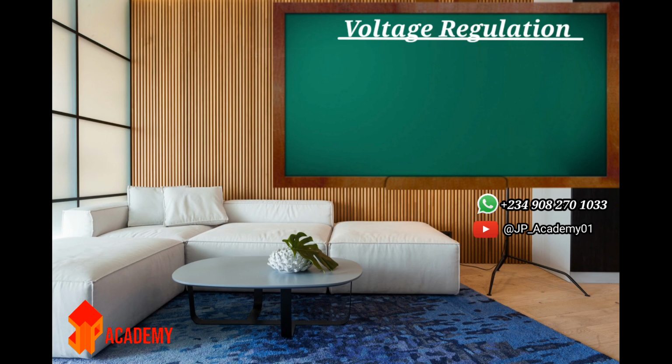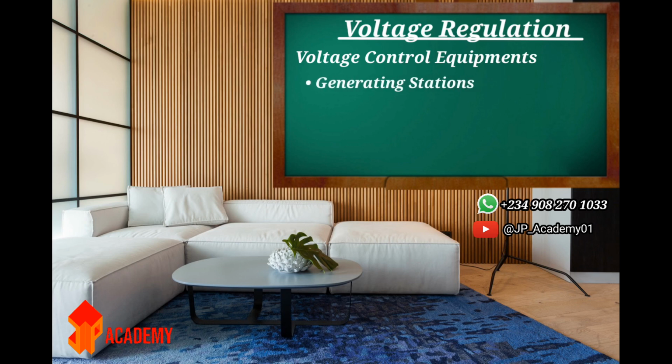This is achieved by installing voltage control equipment at suitable places, such as at generating stations, at transformer stations supplying to feeders, and at the feeder's end if the voltage drop exceeds the permissible limit.